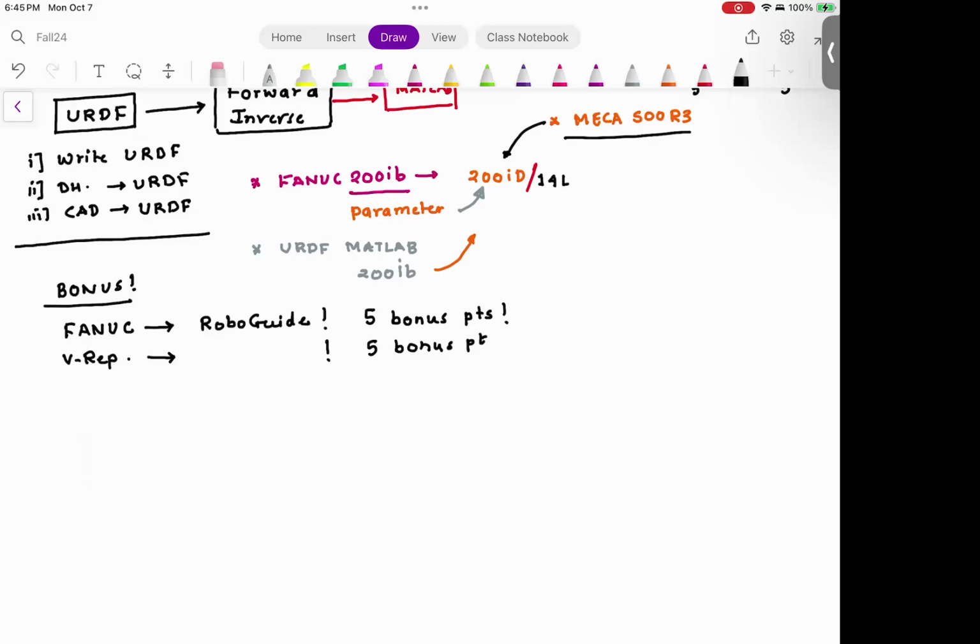It means you are grabbing a part from point A and placing it at point B, but if you do that motion very slowly, static force analysis gives correct results, because you are ignoring the inertial properties or accelerations of that object.